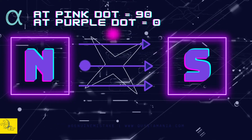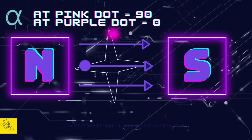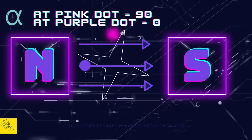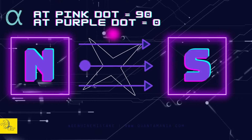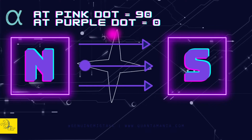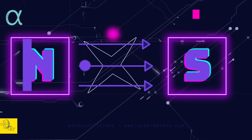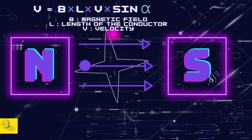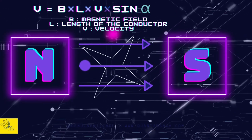Or in other words, alpha is 90. And if the star is at the purple point, then alpha is 0, meaning that we're not making any electricity because the magnetic field and conductor are parallel to each other. So this is one factor that is important for the amount of the voltage that we're generating in this situation.